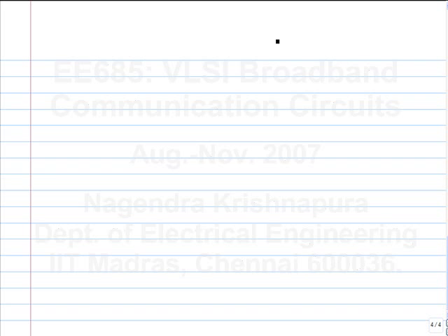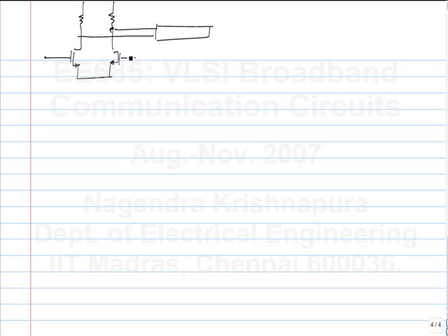What is an approach that I could take? And let me also say that we will be driving similar channels. That is, a channel is basically a differential pair of wires or a transmission line terminated on both sides. So if you didn't need any equalization, this is the transmitter you would use.